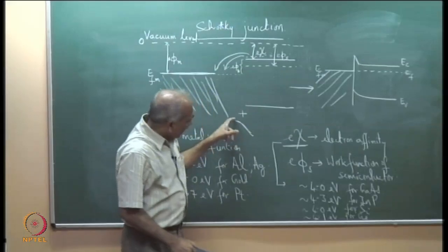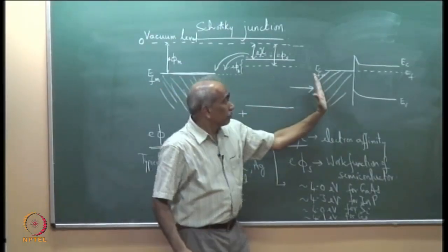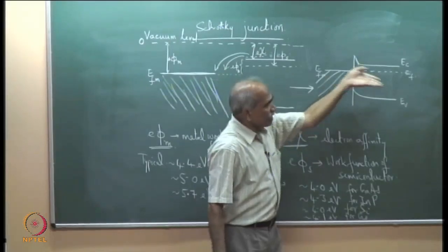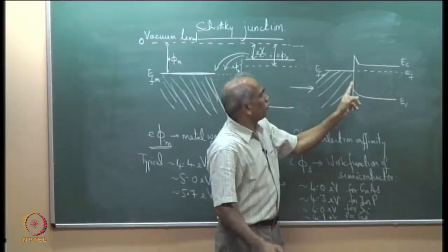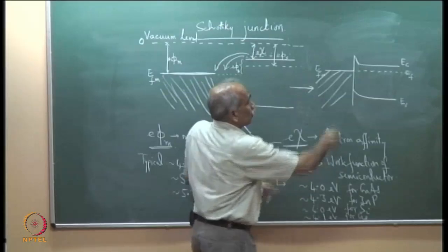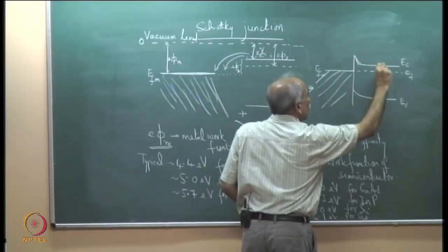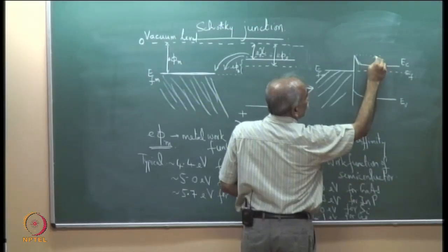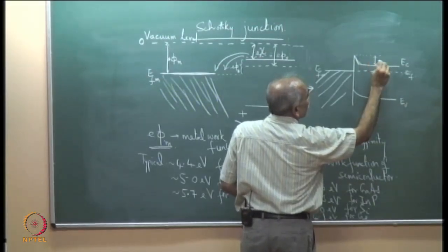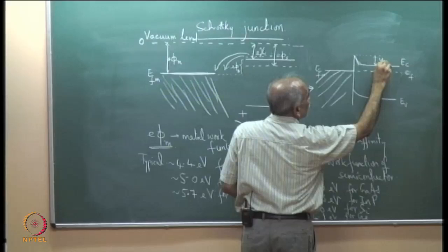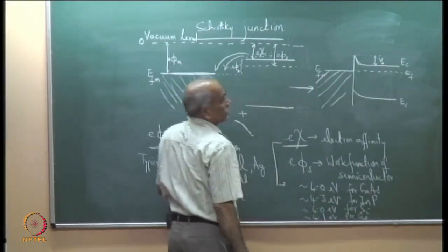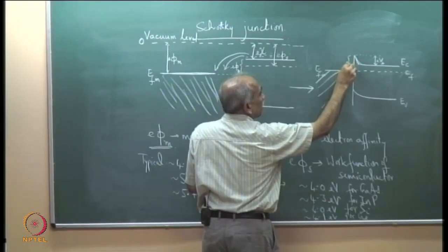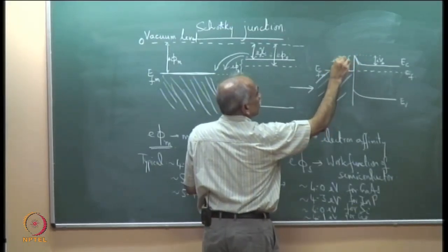But remember there are plenty of electrons. It is as if a p plus and n junction. It's almost like a p plus and n junction. So this side we do see this, and therefore there is a built-in potential here. What do you think this will be? V built in, Vb, or E times V built in. This barrier is called the Schottky barrier, E phi b.